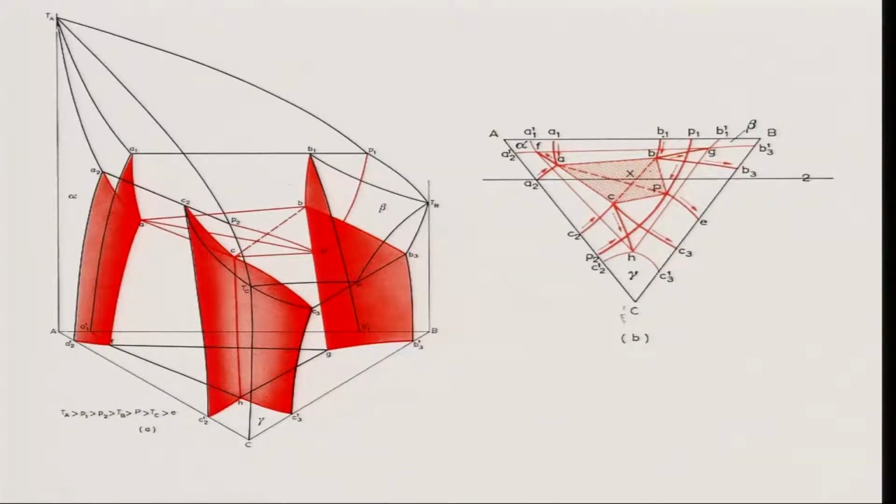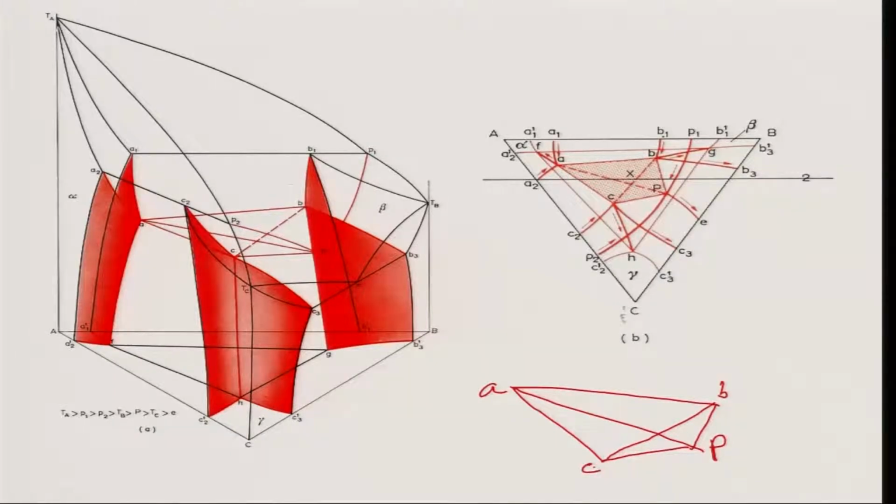So, this inside plane is what I have drawn there, I am drawing again. This is a trapezoid, you can see here carefully, trapezoid, correct. So, this is point P, this is point A, this is point B, this is point C. So, here you have all these planes lying, that much is very clear to you, right. That is how things actually happen in this phase field. Now, one can actually draw even much more complex diagrams where you have 2 eutectic and 1 peritectic, that is also possible.